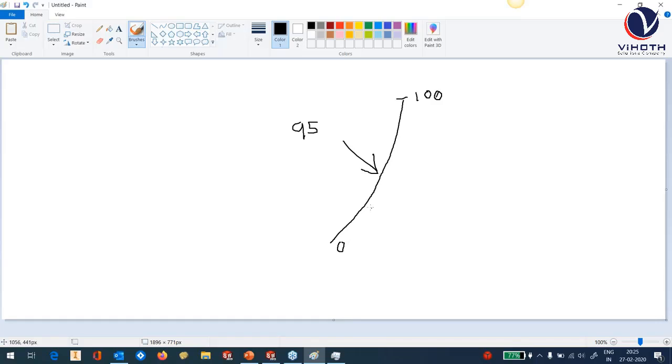So I can specify a point on this barrel profile or oval profile, let's say at 30%, and tell SolidCAM to keep maintaining this point in contact with the surface every time. The moment I specify this point, SolidCAM will automatically derive the tilt angle and maintain it throughout when it's machining the surface. So it becomes much easier.